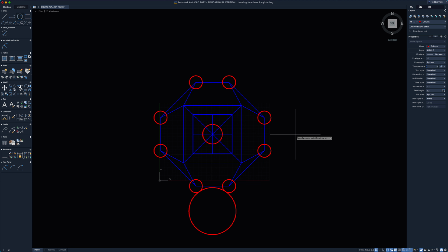So I'll escape out of there, go to the tool set again, select tan radius, select the tan, and now it says my last dimension was 90, so just hit enter, go back to the top, choose my tangent point, and enter, go back to the top, tangent point, and hit enter.